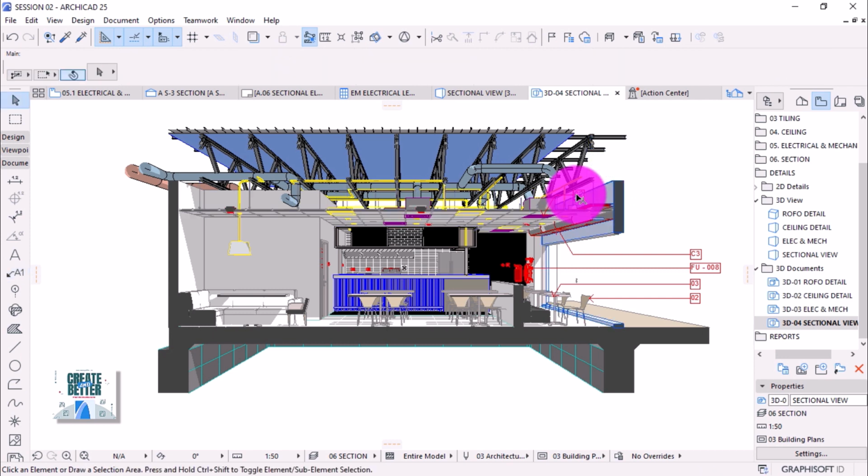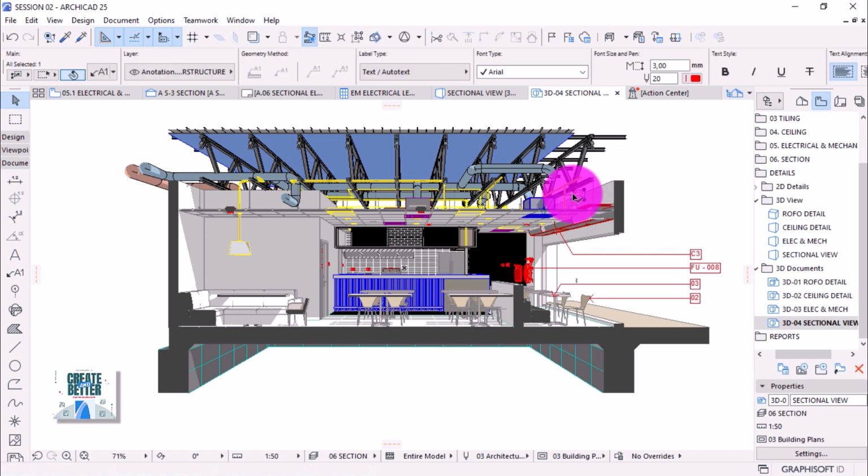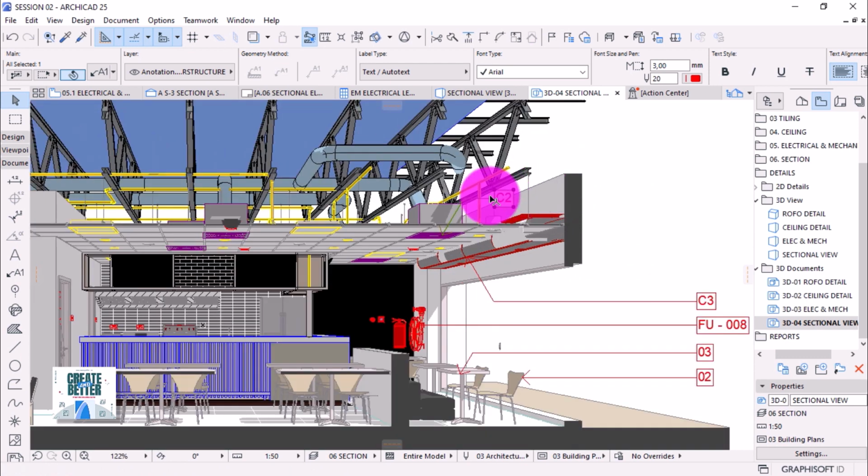Click on the label to stretch it and align it with the other labels, just like that. Zoom in and pick the midpoint of a label to stretch it to there and create the space between.